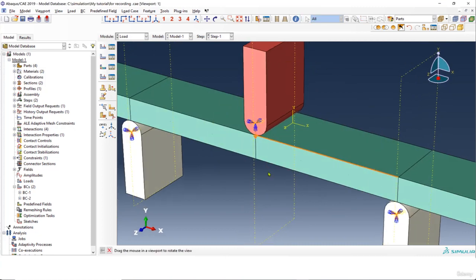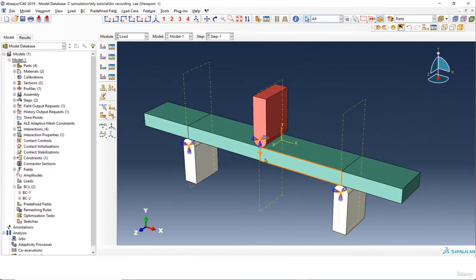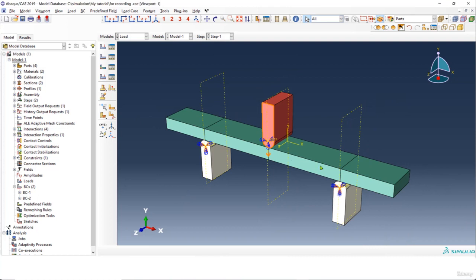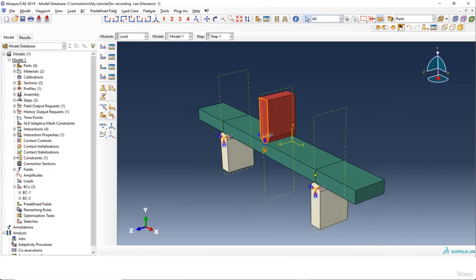and the next step is basically fixing the beam. So in real life, when you do this type of test, you normally have some sort of preload on your sample, so the top fixture holds the sample properly. So when you start a test, your sample won't slide in the Z or X axis.